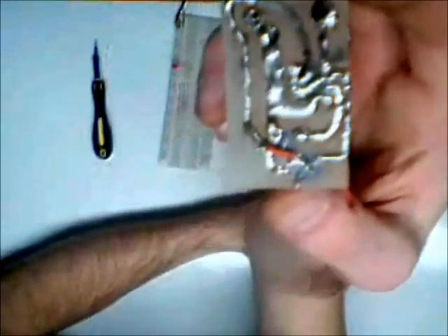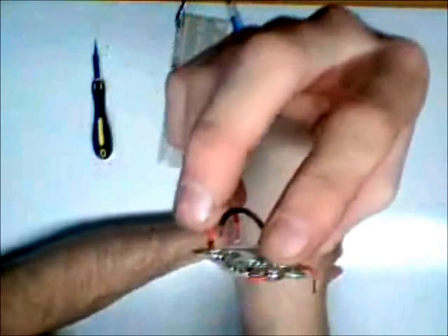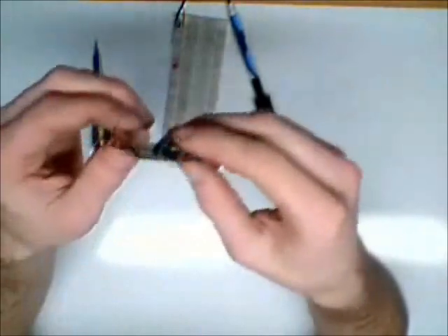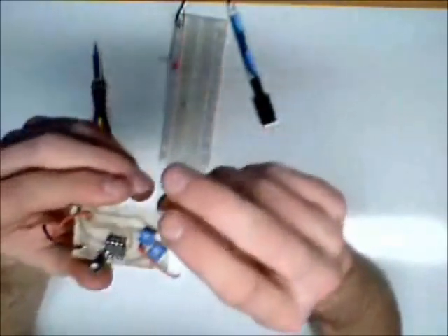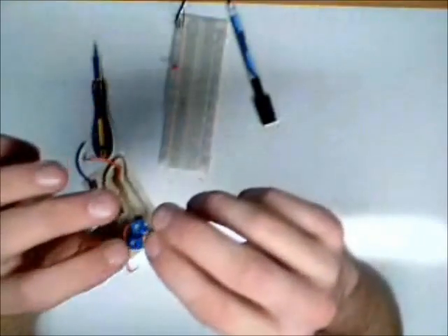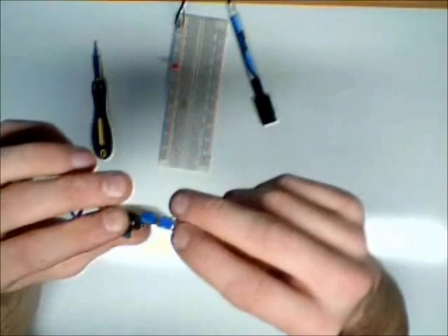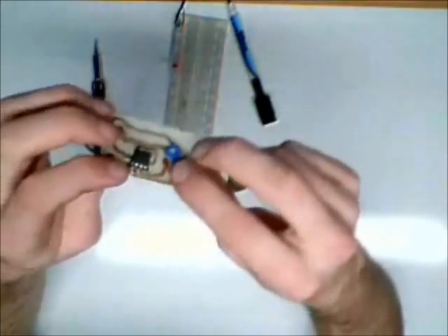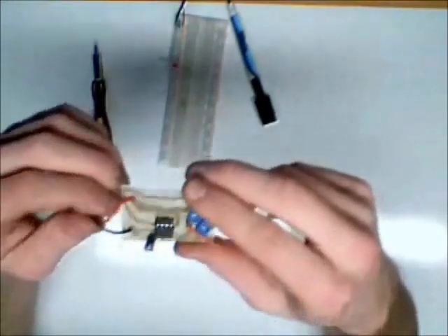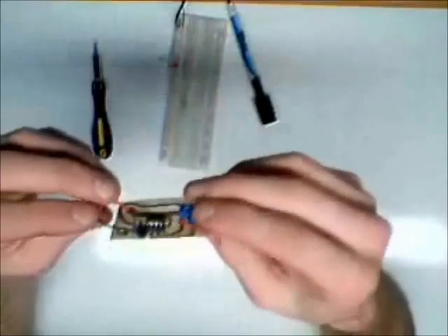And I ran all my traces with a bead of solder just to make them a little bigger, because they're kind of thin. But it works, and obviously it works. I just wish it worked to where I want it to work, but next time I'll put bigger potentiometers on there. If I wanted to, I could just desolder the potentiometers and put a bigger one in for each of them, and I could lower my frequency that way, or change the capacitor out to a bigger capacitor, and that'll lower my frequency. There's a lot of things I could do, but for now I'm just going to keep it like it is and play with high frequencies.